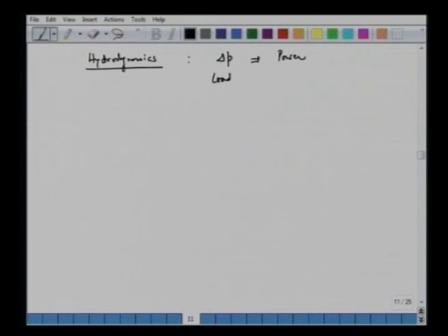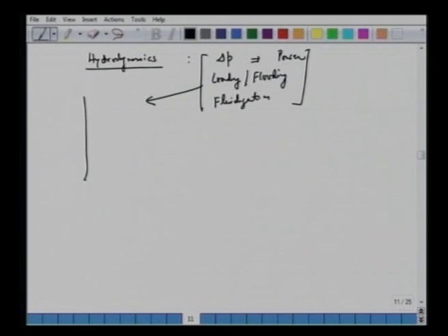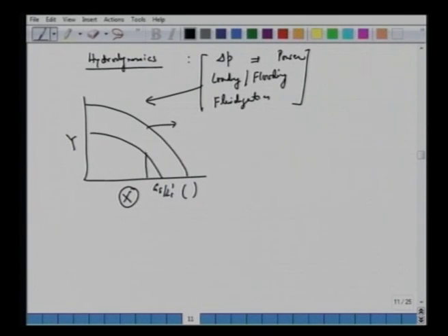One has to be considerate about loading and flooding in case of continuous counter-current process or fluidization. We have not discussed this in detail, except when we discussed absorption, where we had this very popular graph given by Eckert or Sherwood, where we talked of the loading and flooding curve, the different pressure drop curves, y versus x, Gs over Ls, if you recall, and certain other quantities. We said that there is a flooding limit. One has to operate at 70% of this gas or liquid flow rate.